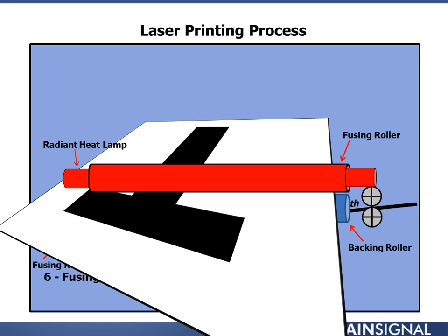Step 1 is cleaning. The idea is going ahead and cleaning off any leftover toner. The way we're doing that is through a process of scraping it off and through neutralizing any charge on the photo drum. Because if it's not charged, then there's going to be no magnetic attraction. Step 2 is conditioning, or some people will say charging.